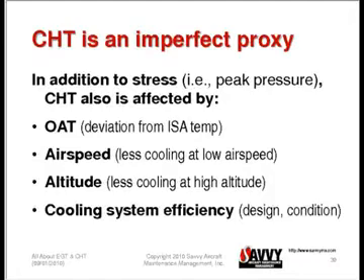So if we're significantly above standard temperature, then CHT is going to be higher. If it's a very cold day, CHT is going to be lower, and we need to adjust our red line and our green arc, if you will, accordingly.